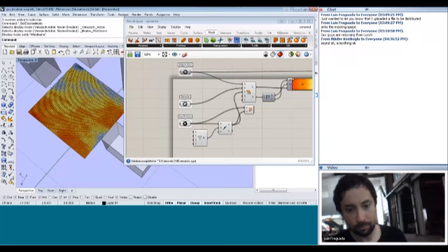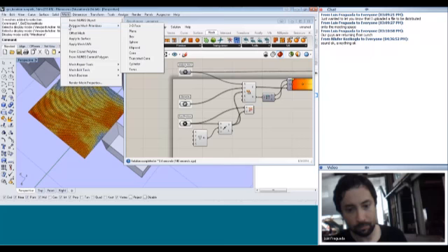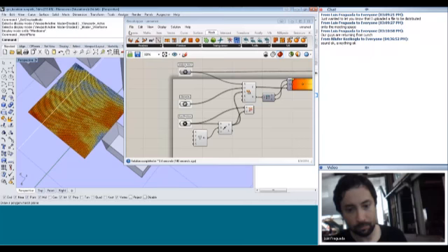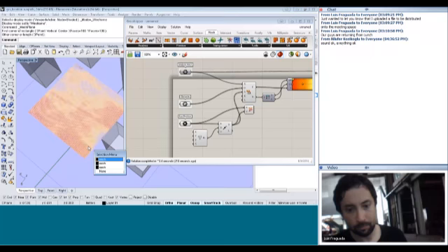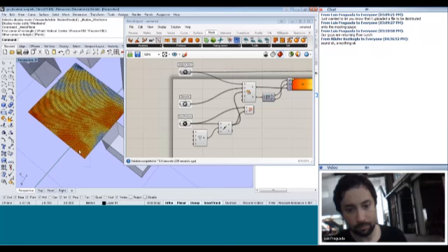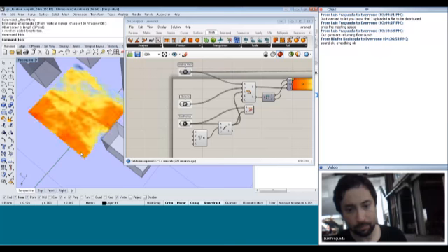Here in Rhino, what I did was I went to Mesh, Polygon Mesh Primitives, and I made a new mesh plane. But here, I'm changing the number of X faces and the number of Y faces to be more. Here I did 100 by 100, and then I just drew the mesh in the same area. So I kind of cheated a bit. But then I took that new mesh and I referenced it for my analysis mesh. But really, that would have been much simpler to do in Grasshopper, with a mesh plane that takes a width and a height. We could do some sliders to see it more dynamically.